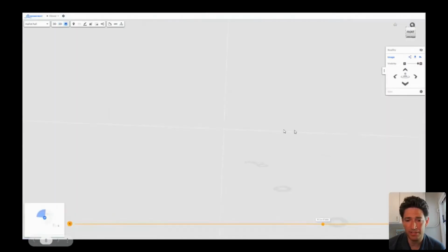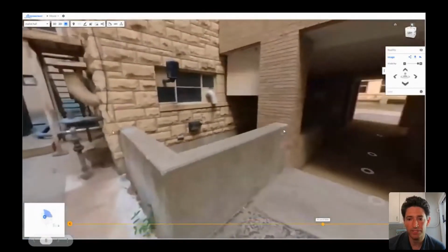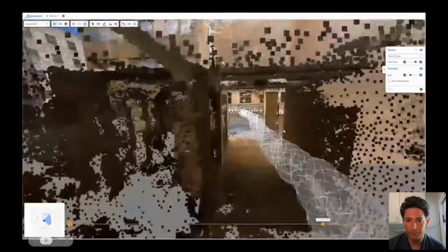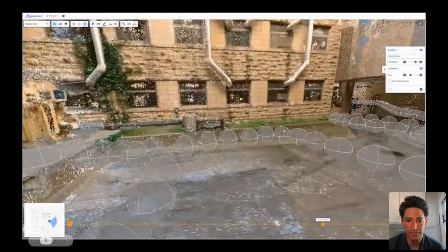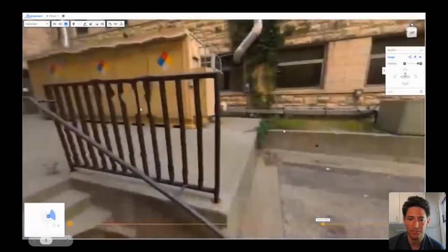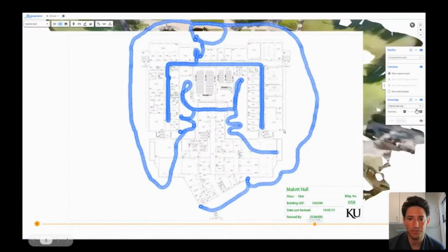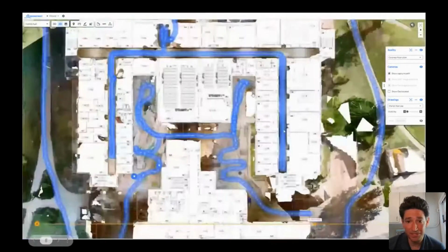Reconstruct doesn't just pin images to a drawing. What Reconstruct does is it creates a reality model. Here you'll see the underlying point cloud model that is generated from all the 360 images, and those spheres that you see are images taken from the 360 walk. Now, why do we do this? Well, we do it for a couple of reasons, but one is to make the Reconstruct models measurable. Measurable means that you're able to take measurements for quantity takeoffs, for various design requirements or validation.